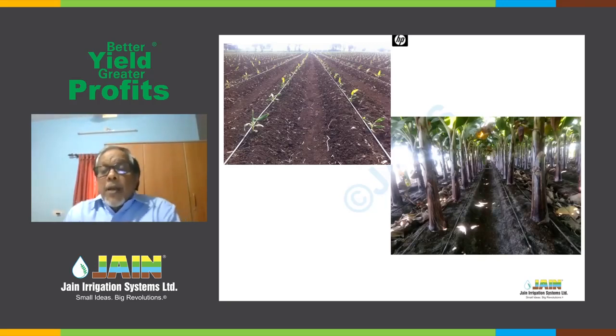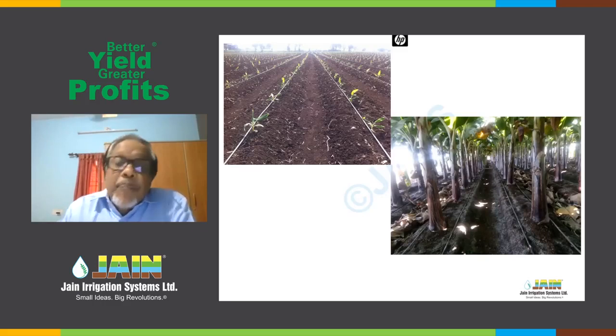That's why in many places, the furrow which you see there will remain dry. In other words, water will not be going down and draining into the furrow. That may happen if we over irrigate without knowing this. Usually in scheduled irrigation, the furrow will remain dry. Only the bed part where the banana roots are located mostly will get wetted.